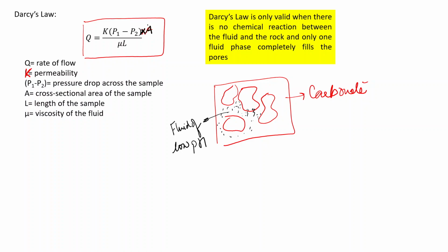So what will happen over here is that Darcy's law holds valid only for the situation where the pore shape and size remain intact, they are not going to change. And the second thing is that only one fluid phase completely fills the pores. So imagine if you have water and oil both in the rock, then the water, being denser than the oil, will behave differently. So there, this Darcy's law becomes invalid.